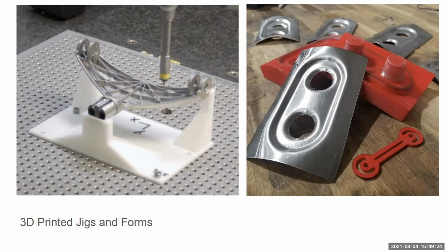And so jigs are just a way for a mechanized construction or manufacturing process to hold parts that are non-standard or non-flat. The one on the left is from, I believe, Dyson. They need to drill and tap a couple different very particular sets of holes in this thing, but since the part itself is wobbly, they couldn't do it with it just resting on that plate. So they 3D printed a jig and then mounted that in the assembly hardware, and they now use that 3D printed jig to hold that part.